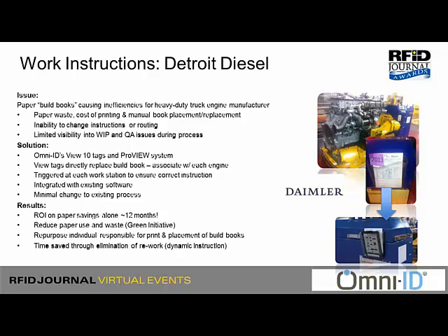But more importantly, it created flexibility that those work instructions could be changed directly. We had a large manufacturer that had a desire to change quality instructions, that if an O-ring didn't seat properly on inspection at the end of the line, they wanted to be able to change the instruction at station number 2, where the operator was seating that O-ring, to say specifically, place the O-ring in this particular way, double check that you've put grease under this part, and press the button to confirm you did that. That kind of interaction you can't do with paper. But that allows them to catch quality problems immediately rather than waiting until the next day and realizing they had a problem on a whole batch. They can correct things in real time.